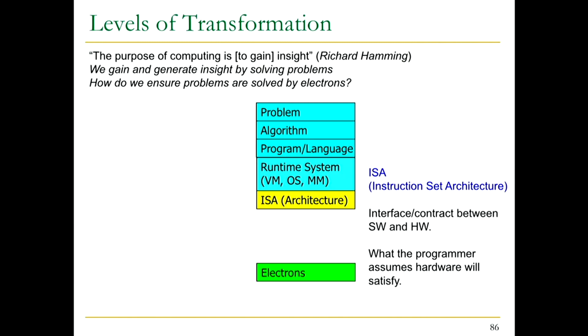In fact, there used to be this VAX architecture, virtual address extensions, which later transformed into the Alpha architecture, but it had three-dimensional array checking. So if you have a three-dimensional array, you actually need to do checks on all of the boundaries, right? X, Y, Z, all of those directions. And it had an instruction that enabled you to do all of this in hardware very, very quickly and very efficiently. Okay, so the ISA specifies what your hardware can do for you.